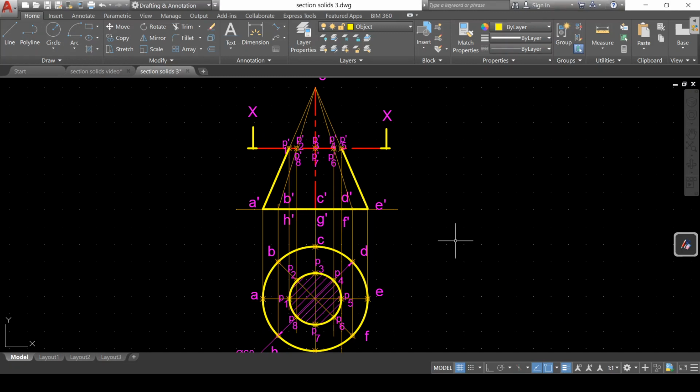We have already discussed in the first session on this content how to get this sectional view. So this has been drawn accordingly. Now we have to develop this cut cone. For that purpose, let us draw the development for the uncut cone and make the changes accordingly. This OE is parallel here to XY. So this slant line is giving you the true length. O dash E dash is giving you the true length of this generator. Sorry, it's not an edge, it's a generator. And we have got the true length of the generator, so we will copy this directly.